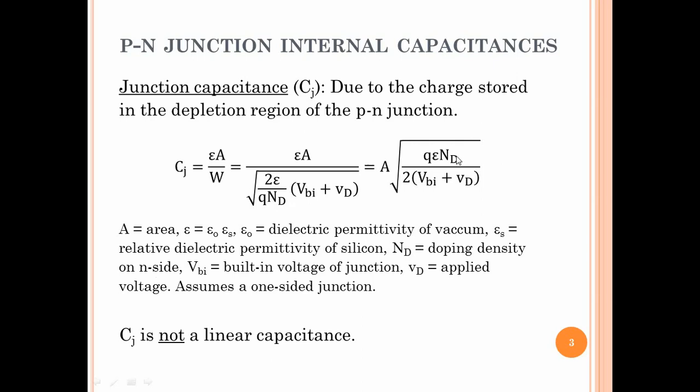In a bipolar transistor, actually, both the junctions, in an NPN transistor, the base emitter and the base collector junction, one side is much more lightly doped than the other side, and this will be the density of the lightly doped side. In any case, we are not ever going to use this expression for this course. This is just for your information that this expression looks like this.